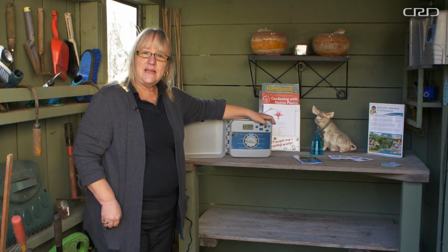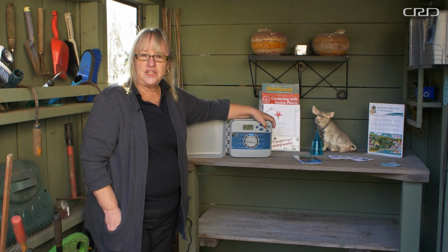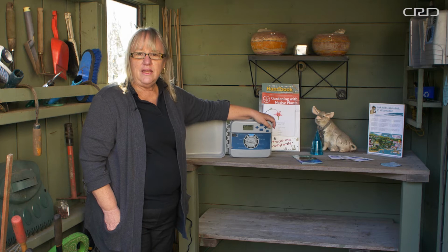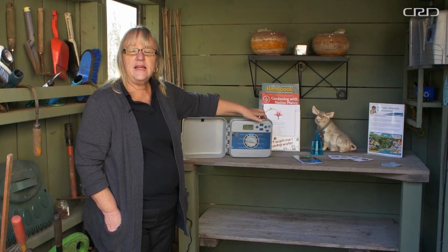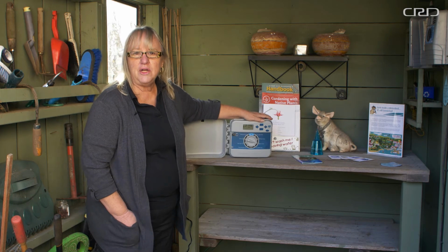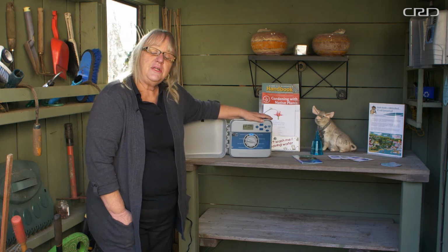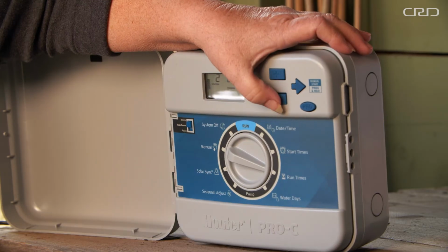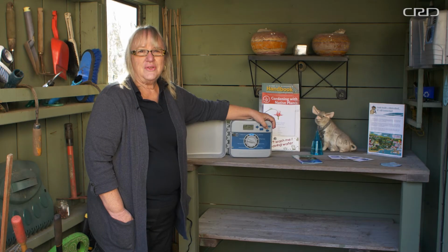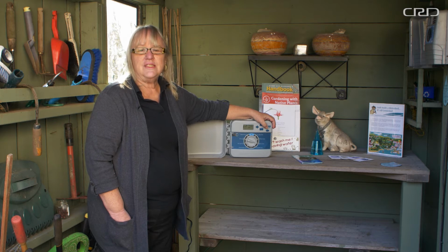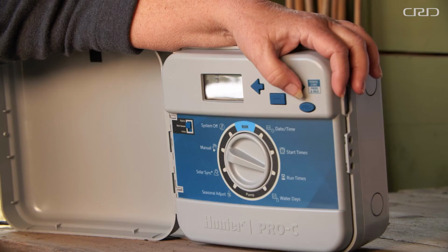when that one is set, I go to my second station. By using my right-hand arrow, it automatically takes me to the second station, and I set my time there for how long I want it to operate. This one I may want it to operate for 6 minutes. So I use that arrow to keep going through all my stations until everyone has time on it that I want to operate under this program.